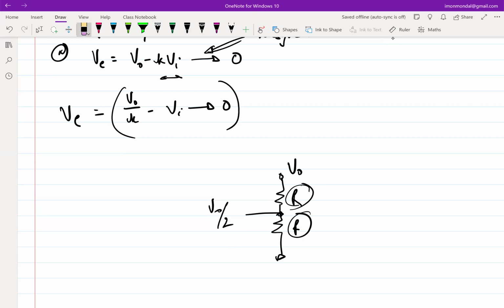Okay. So as it turns out, making very well matched resistors is not so difficult in an integrated circuit, because ultimately in an IC you place things very close by. And if you are making these resistors out of the same material, built in the same way, laid out in the same fashion, then it makes sense to argue that one resistor is almost similar to the other. And in fact, that is true to quite a large extent in an integrated circuit, where you can make ratios of less than 1 independent of ambient changes, right? So now we have the setup.